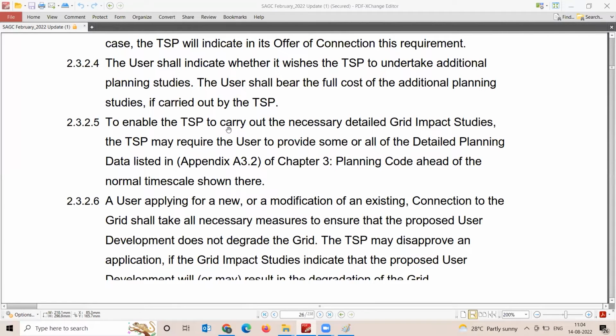Since electricity cannot be stored, the generation and demand have to match at each and every moment. It's the responsibility of the dispatch utilities to manage the generation and demand. When you inject heavily and when you reduce it drastically, some other source has to meet this mismatch and the dynamic response. That's the reason why large scale solar plants will have certain constraints on ramp up or ramp down capabilities.